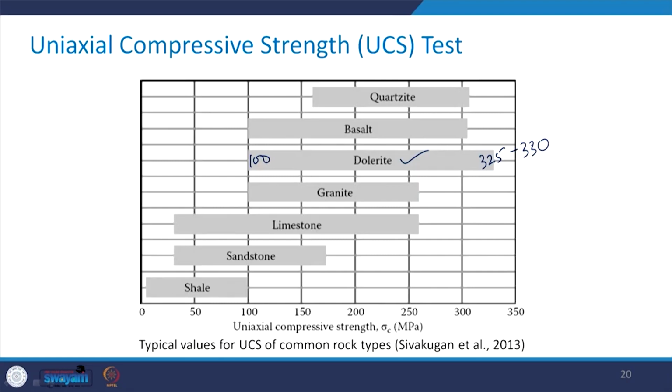And it is really not possible to quantify these micro cracks, that if there are 100 micro cracks, then the strength is going to be this much, and if there are 200, so on. There is no way that we can find out the exact number of those micro cracks, because those are not the fractures or the joints. Those are an inherent property in any rock, even in intact rock they are present. So depending upon their orientation and distribution, this randomness is there in the behavior of all the rocks.